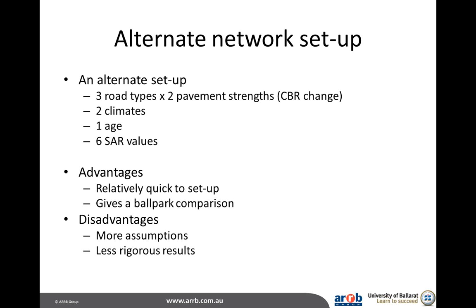The advantages of this type of setup was that it was relatively quick to set up, and it gave us a good clear ballpark comparison of how these different roads might react to increase in loading. The disadvantages were that there were a lot of assumptions required. Our pavement strengths were simply developed using material coefficients and thicknesses to calculate those strengths rather than having real data to input into that. So we end up with a less rigorous result, but it has a lot of potential for doing quick analyses.